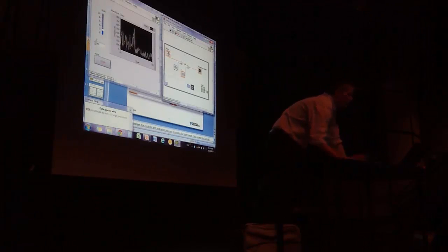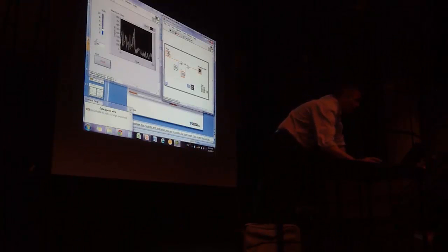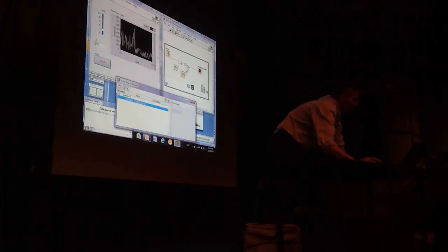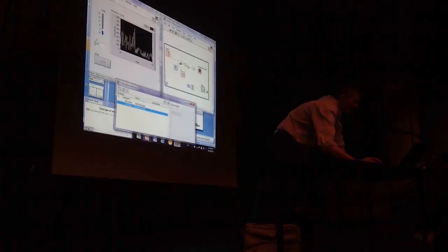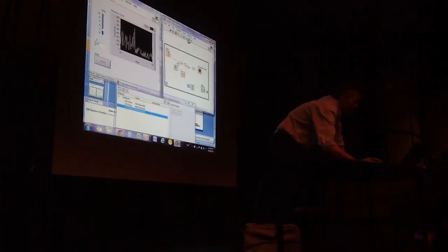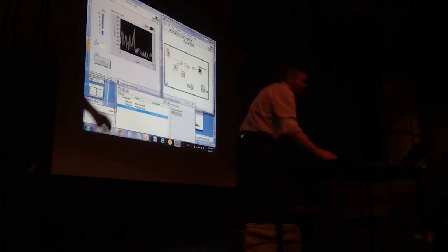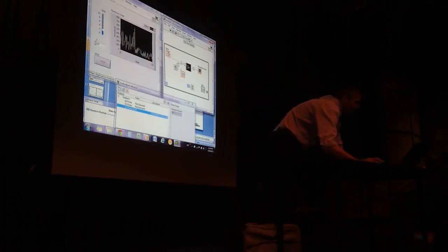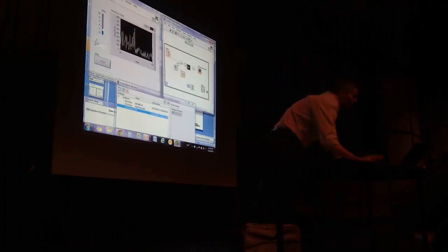What I can do as well, if I go now over such a wire, I see it's a probe, so I can drop the probe so I know what kind of values I have. So I step over here. We see now the probe number 3 is now 34. And if I go now over to the slider, it's now 69.38, and so on.